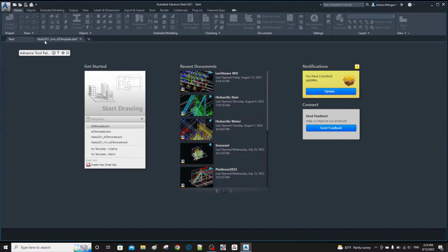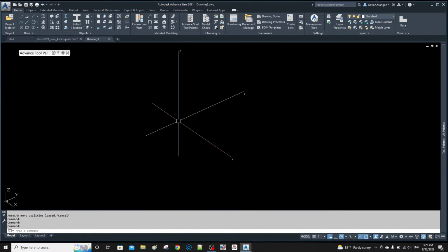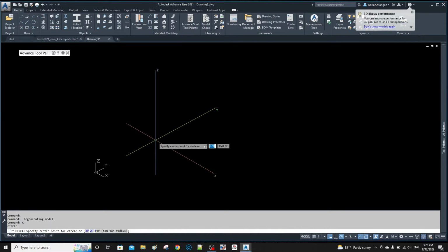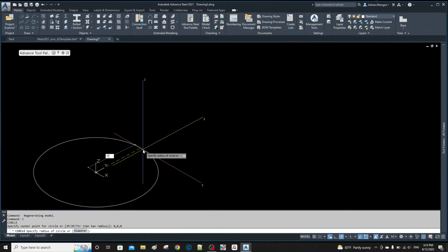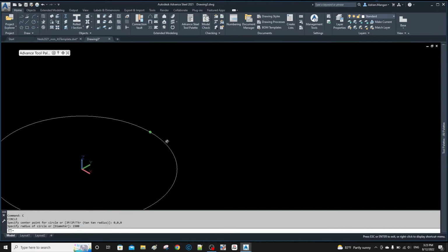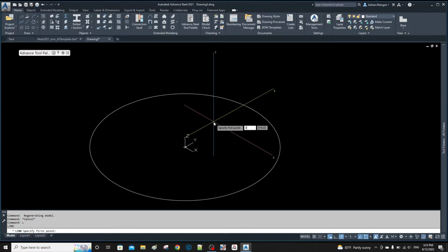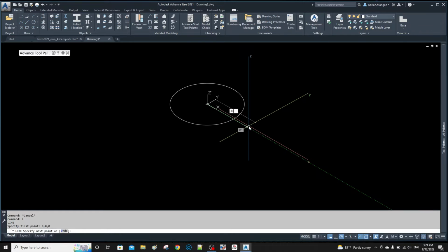So what I'm going to do is, now I'm going to go back to this one, which is the out of the box template, which has nothing here, right? So what I like to do is just draw something to locate the origin. Now I can't do 5 feet obviously, so 5 feet is about one, I'll do 1.5 meters. And then let's draw a line from 0, 0, 0. So this is the second way, just in case you missed it. So let's do 3 meters.